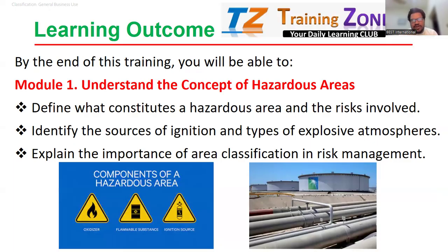So minimum up to 6 meter, maximum up to 10 meter, consider it a restricted area. So any activity within this area, you have to be careful. No heavy equipment nearby, no person should go, and the whole area must be barricaded in the shape of a line of fire to be defined through barricading. And of course, if we are going to perform any activity, since it's a restricted or hazardous area classified with zone 0, zone 1 or 2, we cannot go without a permit. And the permit should never be issued until we have lockout, tagout, and isolation.